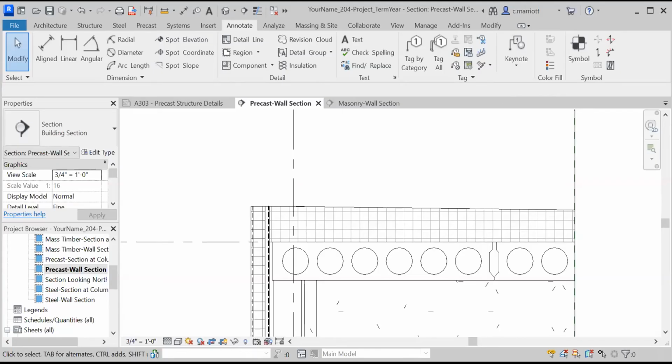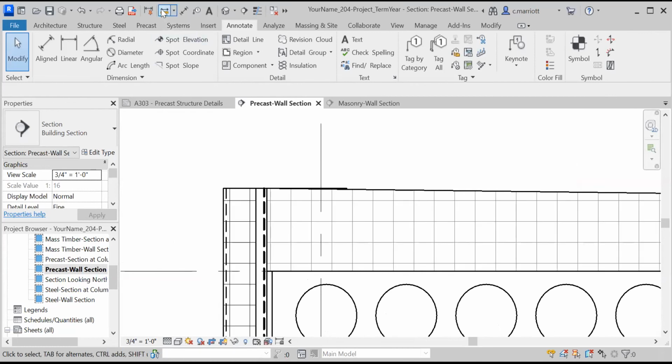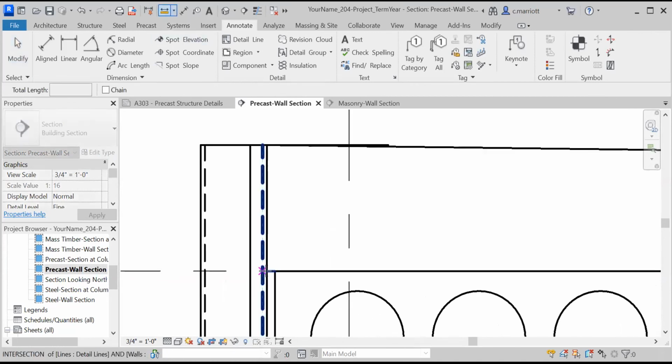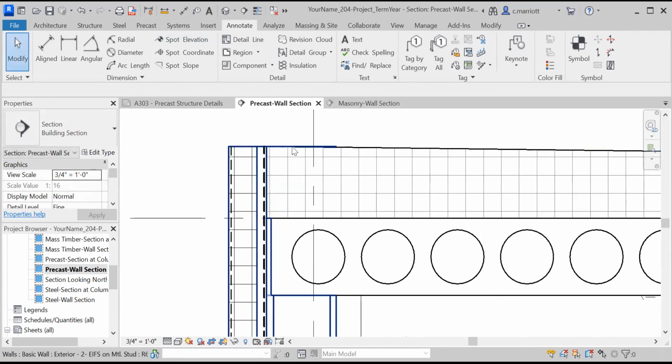Now, based on the pitch of my roof and wanting to maintain 1/4 inch per foot, when I come over to the edge here and I measure the thickness of the insulation, I get 7.5 inches. Okay, so I'm going to need to build up a sort of curb at the edge here to have something to attach the gravel stop to.